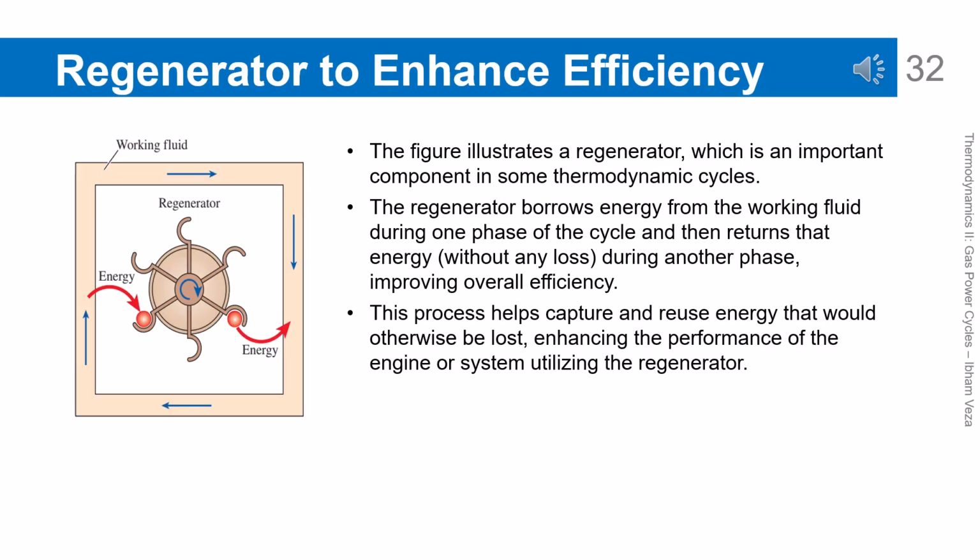A regenerator is a component that temporarily stores thermal energy from the working fluid. This heat is then returned to the fluid at another stage of the cycle without energy loss. In this way, the required heat input from external sources can be reduced. The result is an improvement in the overall thermal efficiency of the cycle. This concept is very important in Stirling, Ericsson, and regenerative Brayton cycles.